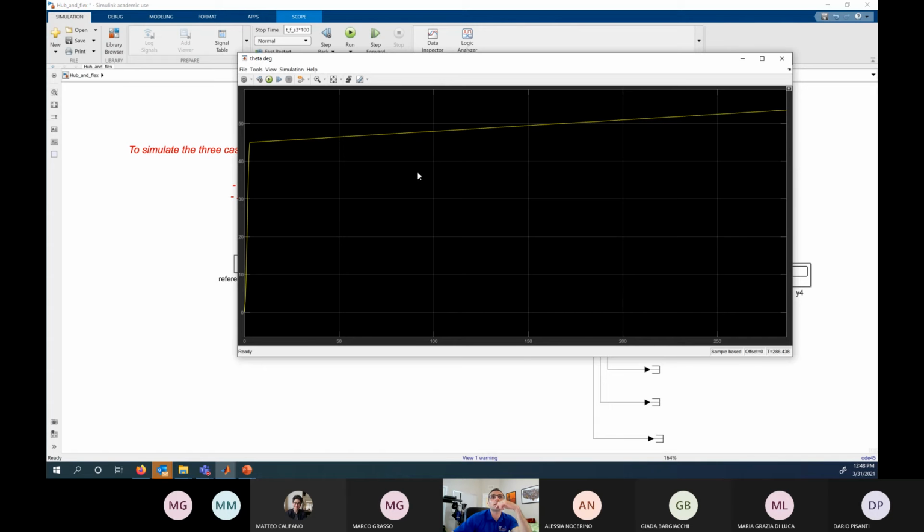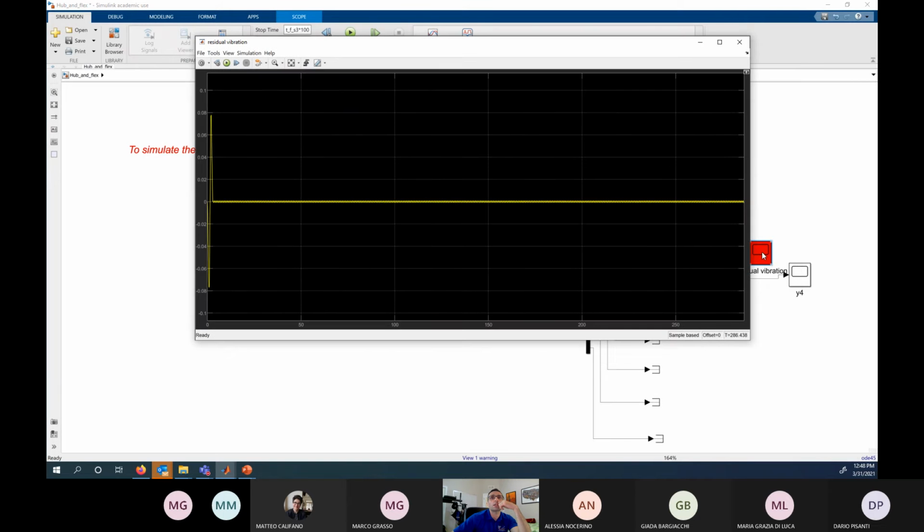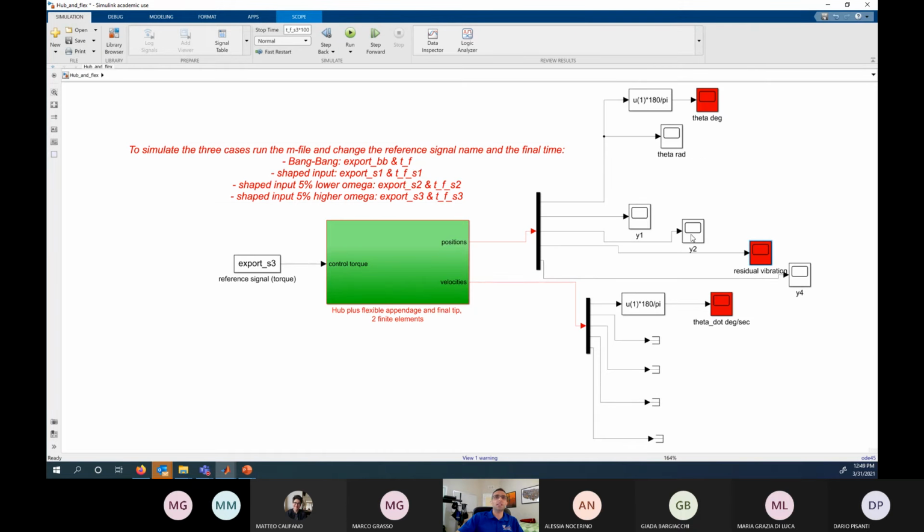And it goes back to killing the frequency. I mean, you're being conservative. You think that there is more flexibility, and so you're definitely doing a better job on the oscillation, but you're only focusing on the first mode. So you could shape your bang taking into account more frequencies and basically try to avoid this initial behavior, because this is really what's causing your misalignment and drift at the end.